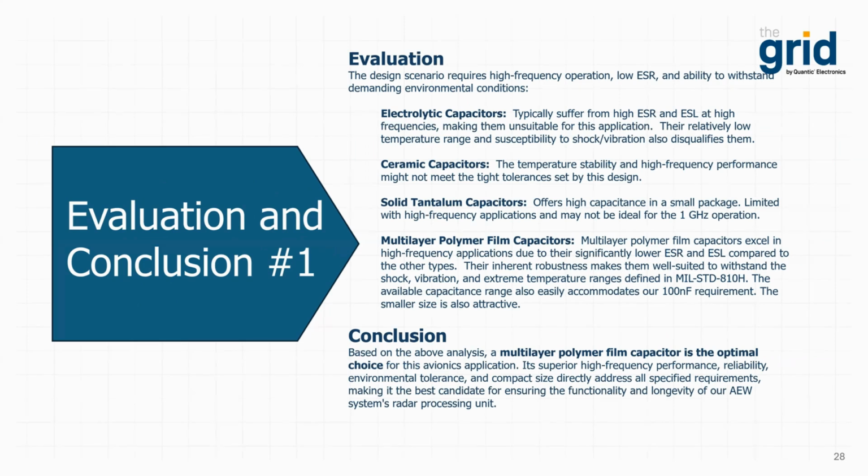Lastly, multi-layer polymer film capacitors, or MLPs, excel in high-frequency applications due to their significantly lower ESR and ESL compared to other types. Their inherent robustness makes them well-suited to withstand the shock, vibration, and extreme temperature ranges defined in MIL-STD-810. Furthermore, polymer film capacitors generally demonstrate high reliability and long life, aligning perfectly with our 10-year operational goal. The available capacitance range also easily accommodates our 100 nanofarad requirement. The smaller size is also attractive.